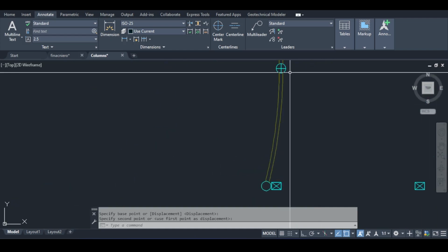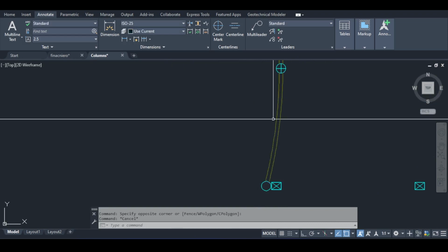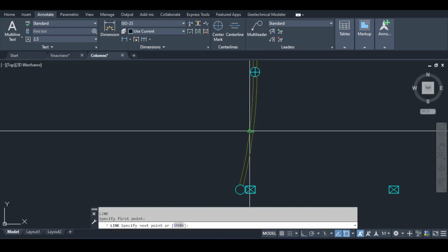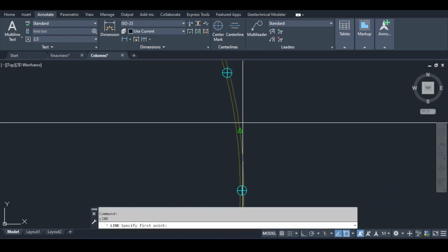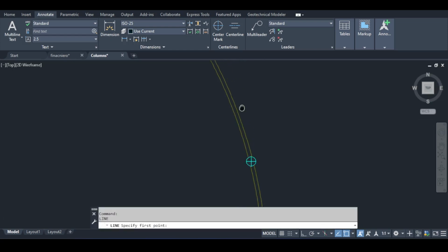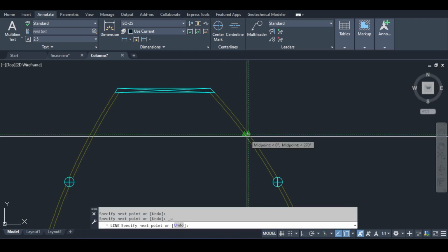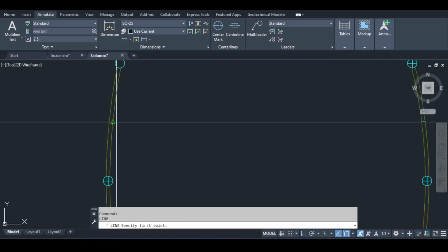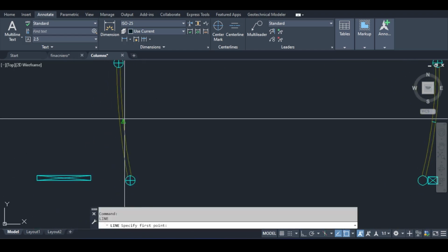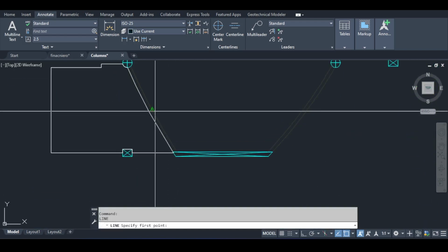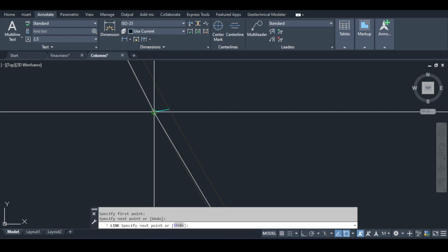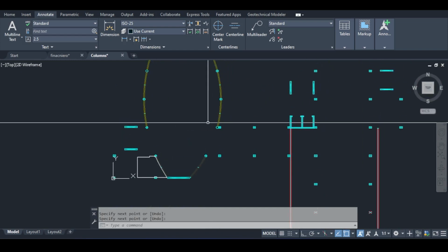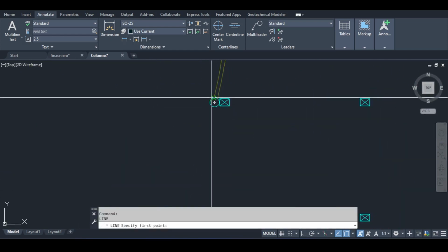Now, I don't know if Robot will see this arced polyline or not. I don't want to go through any chances. So what I will be doing is, first of all, I will draw a helper line. So I'm drawing basically the center of each arc. Those are two arcs because architectural drawings draw the thickness of the wall. For us structural people, we don't care about the thickness of the architectural wall, not the shear wall, of course. And I will just draw a center line to help myself align the drawing in Robot. Because if I remember correctly, and I might be wrong, we will see this today, I think that Robot does not see or show arced polylines. Also, I need to deal with this in center-to-center fashion.